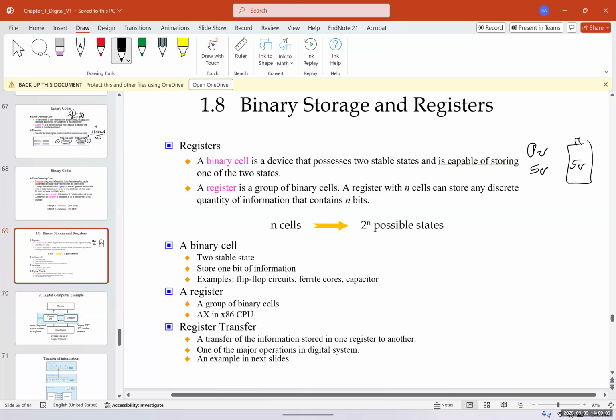A lot of the memories that we have are short-term memories, like the memory in your computer, the RAM. They only hold the value as long as they are powered. As soon as you cut the power or reset it, it's going to be erased. That's called random access memory. Some memories are permanent, like a CD, DVD, or a hard drive. Flash isn't quite permanent, but it holds data for a long time. Even if you cut the power, it retains the memory.